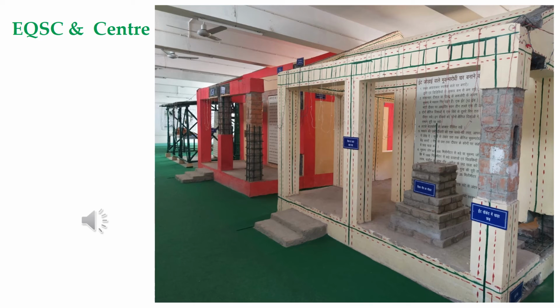For any type of masonry structure, generally one or two story buildings, we prefer this methodology of reinforcing or stiffening the wall openings or foundation level. This is a very effective way of making a resilient building with respect to earthquakes.